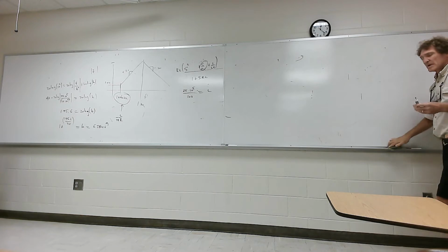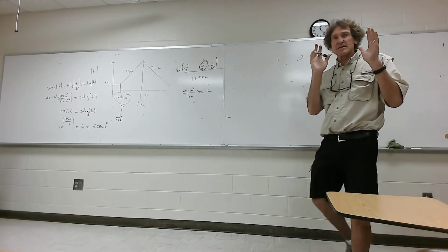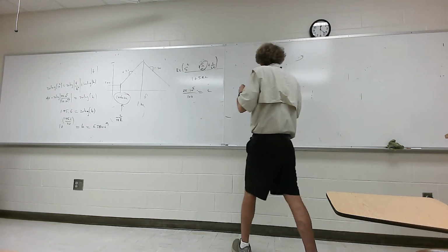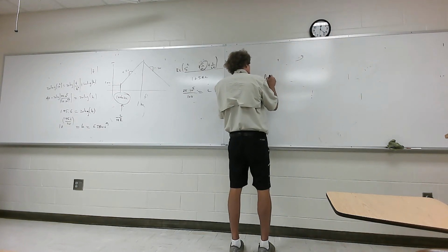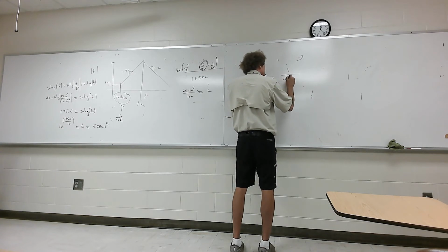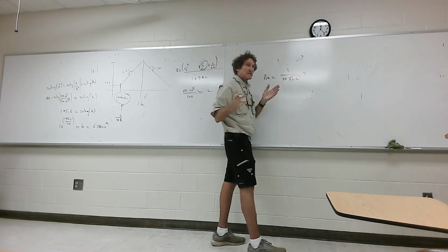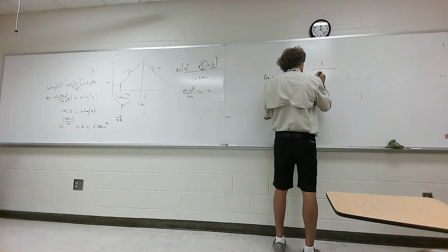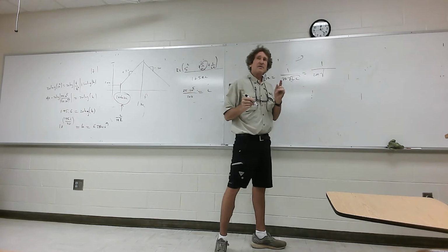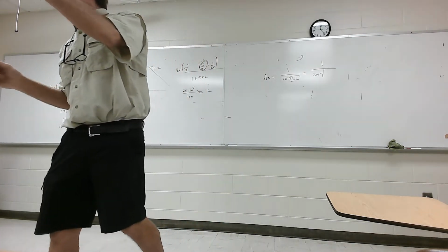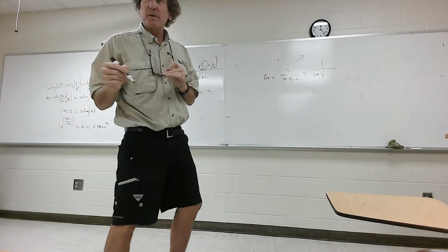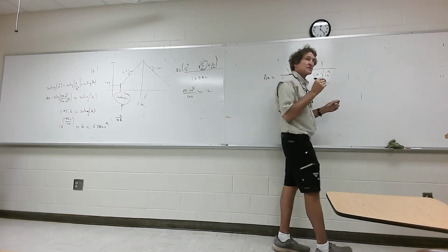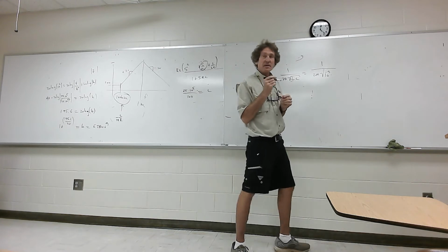Just for kicks, I want to check one thing. See if this resonant frequency based on their values agrees with 1 megahertz. The resonant frequency is going to be equal to 1 over 2 pi square root of LC. That's going to be true. So he has 1 over 2 pi square root, and his value of L was 1 nano, 10 to the minus 9. So it's 10 to the minus 9 times, what's the value of C? 1 micro. 10 to the minus 6.